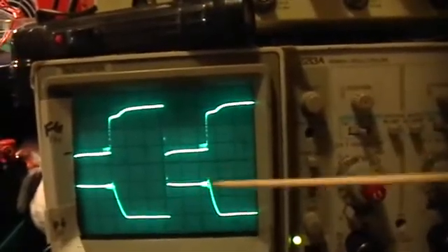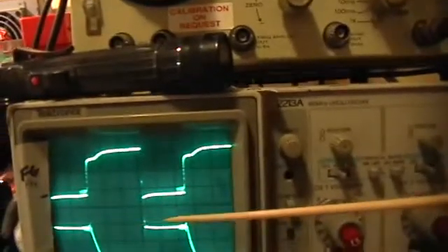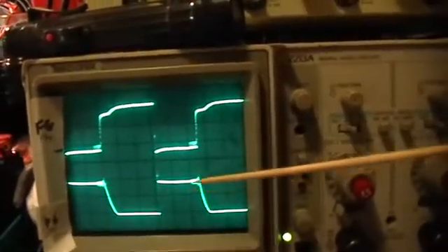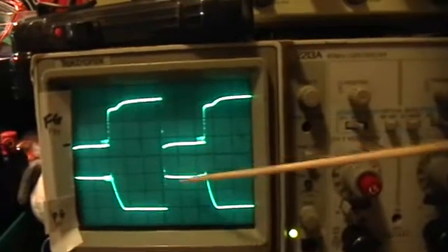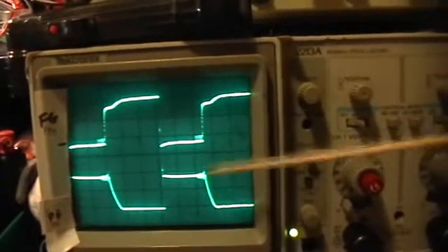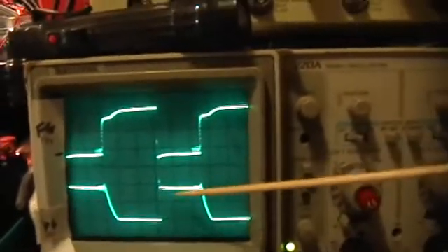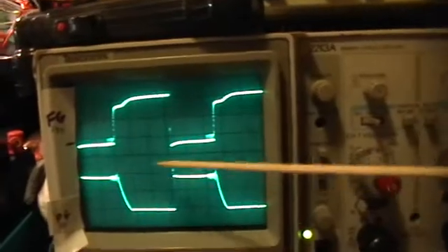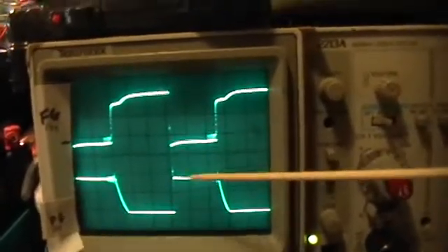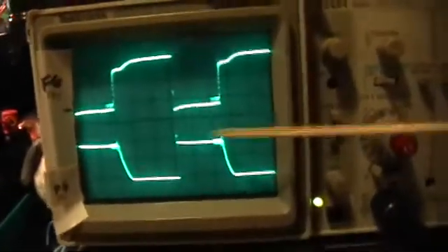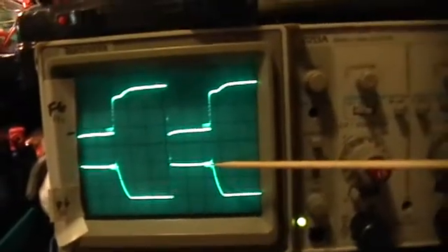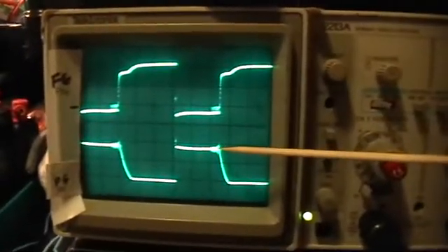So once again, if you can increase that oscillation, what that means is that the MOSFET is actually on during the time when it's normally off. It's on a little bit and it's leaking. Okay? So no wonder you think you're getting more power through during the oscillation, because you are. The MOSFET's actually partially on even when it's off, and once again, that's the definition of a parasitic oscillation.